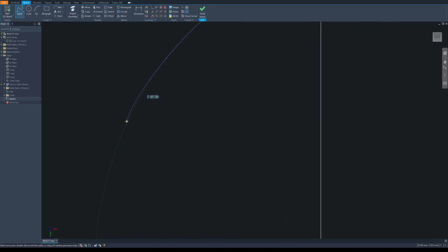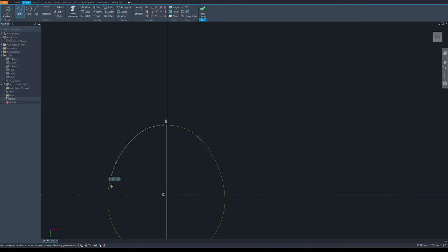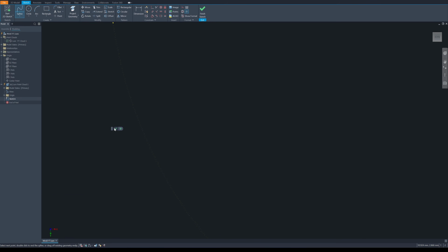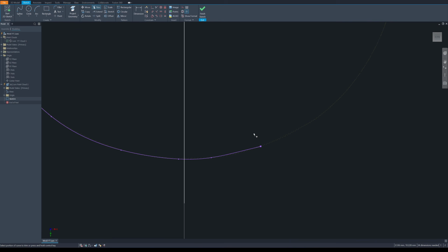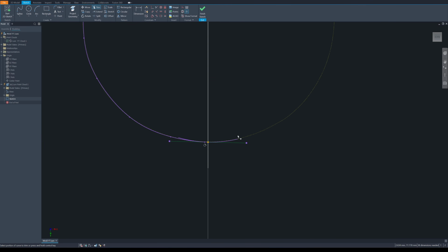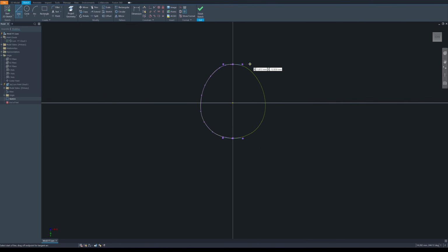So it's quite easy to use the spline to trace an arc like this. If your point cloud is thin, this one is less than 20 microns, I think around 7 or 8 microns, then when you put your mouse on the wall, it's going to be very precise. This fishing lure doesn't require that much precision because it's not going to attach to anything. Okay, next I'm going to trim this. I draw it past the center line and then I trim it. And I'm going to draw a line here.